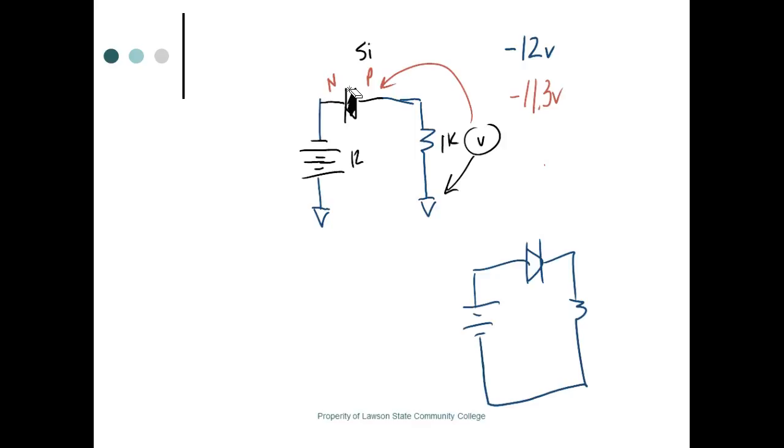So make sure you first determine if it's forward bias or reverse bias, right? Y'all understand that? When it's forward bias is when you're concerned with what type of diode it is. When it's reverse bias, it makes no difference, because when it's reverse bias and it's in a series circuit, it's going to drop the applied voltage.